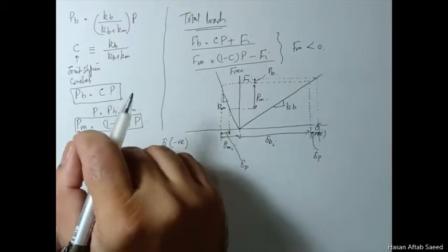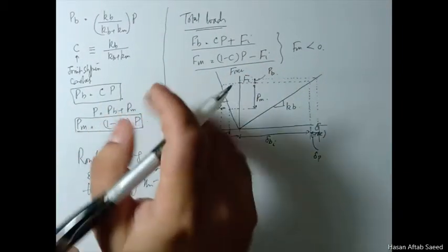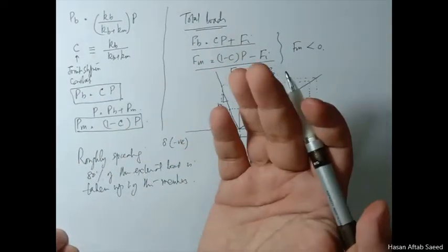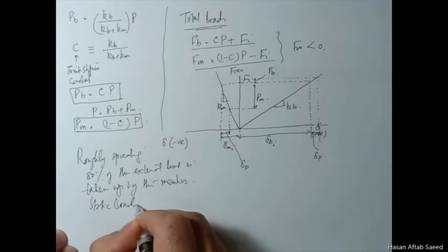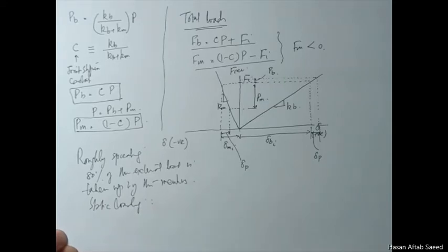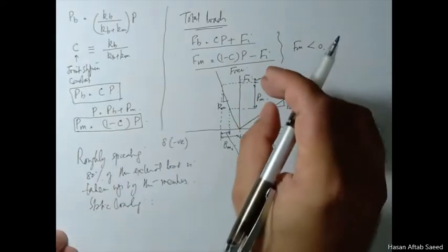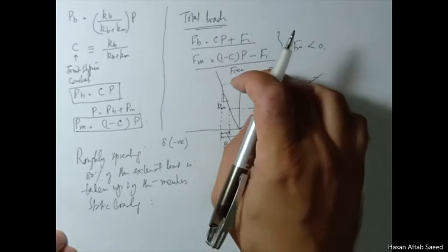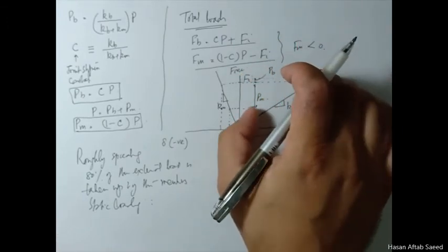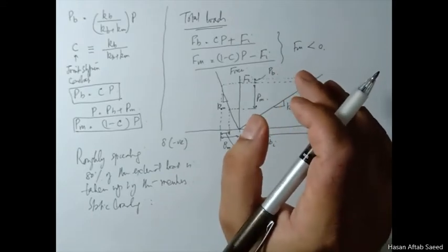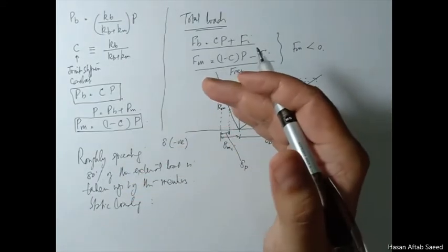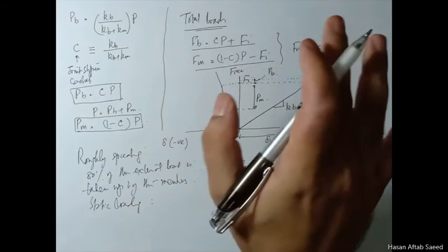Now this has consequences both for static as well as fatigue loading. For static loading, you can use much smaller bolts. Why? Because you apply a loading of Fi, and that is a requirement. You preload all the bolts, but you don't worry about it because you can go very near the material strength, and we'll talk about that later on.